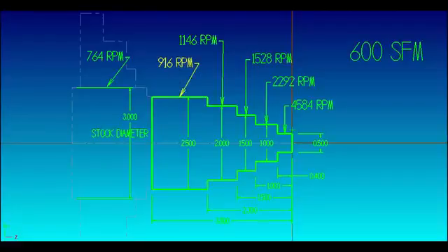So you can see it would be hard to determine just an RPM that would work for all of these diameters and expect good tool life and good surface finish. Instead of doing that, just tell your machine to maintain a 600 surface speed, and the machine will automatically adjust for all these diameters. So let's talk a little bit more about why to use constant surface speed.